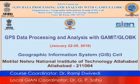That full matrix is used. That's again what takes time. That's why the time series analysis programs like TSFit, which operate on one station at a time, are so much faster, because they're not carrying all the covariances between all the individual stations. They're just treating each station by itself. GLOBK is carrying all that covariance information, and that's what makes it slower, because it has to do all that calculation.